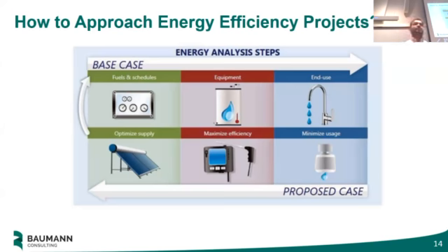For an energy efficiency project, assuming we are doing an energy audit for a particular building, we go into the facility, assuming you are coming into this room right now. You enter the room and understand what the heating and cooling loads are. First you understand the sources of fuel. You have electricity for lighting and air conditioning, and if you have heating, natural gas. Those are the two fuel types. Next, we understand the equipment: we have the lighting, the air conditioning, and the plug loads through computers. Those are the different equipment that contribute. End users again include all the plug loads and so on.